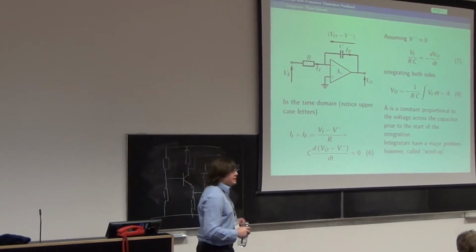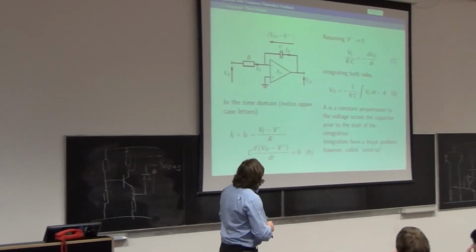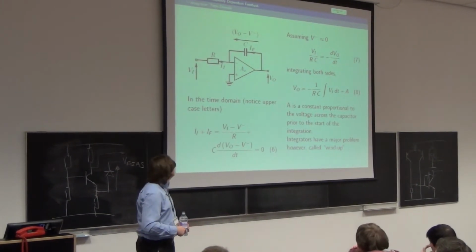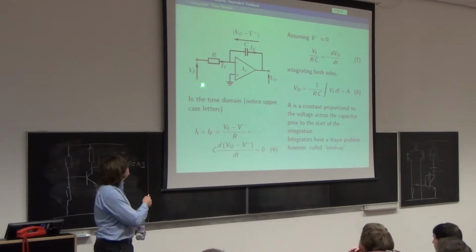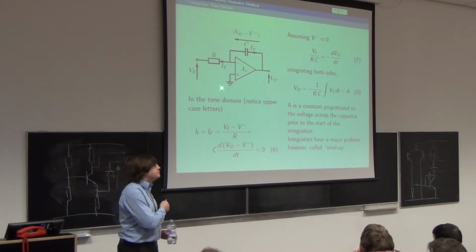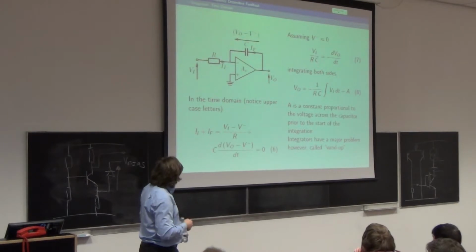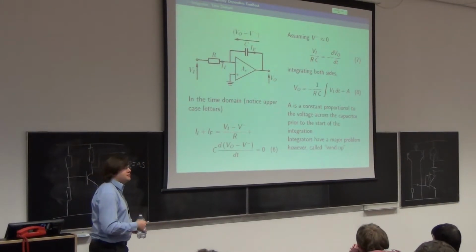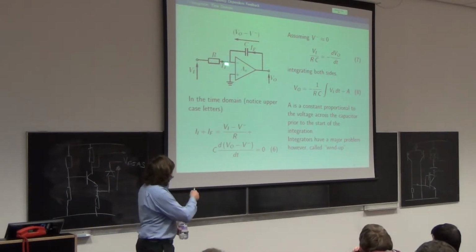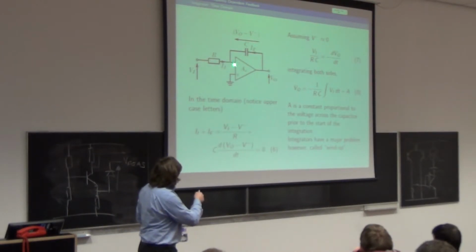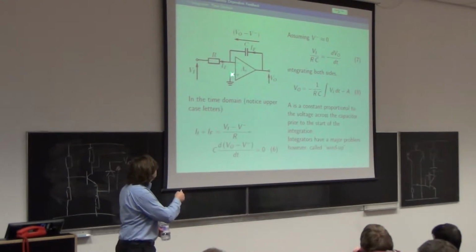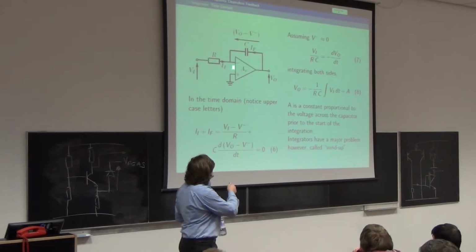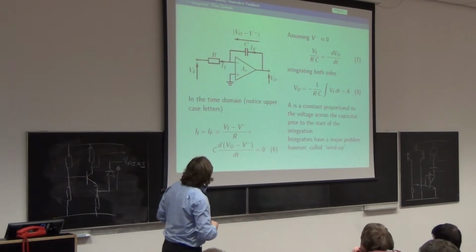So that's frequency domain. In the time domain, we should get an integrating function. There's no difference here, it's just all the letters have got big now. They're uppercase rather. So we'd use the same sort of analysis that we would use for a regular op-amp. We'll say that this current and this current have to equal each other and there can't be any current in there. And that these two are equal to each other. These two not quite equal to each other but jolly close.